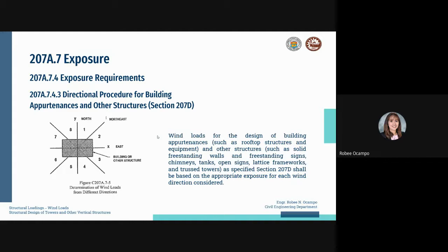If you have 8 wind load cases, you also have 8 versions of load combination 4, because you're considering one load case per load combination. So however many load combinations you have with wind load, multiply that by 8. That is how many load combinations we will have.